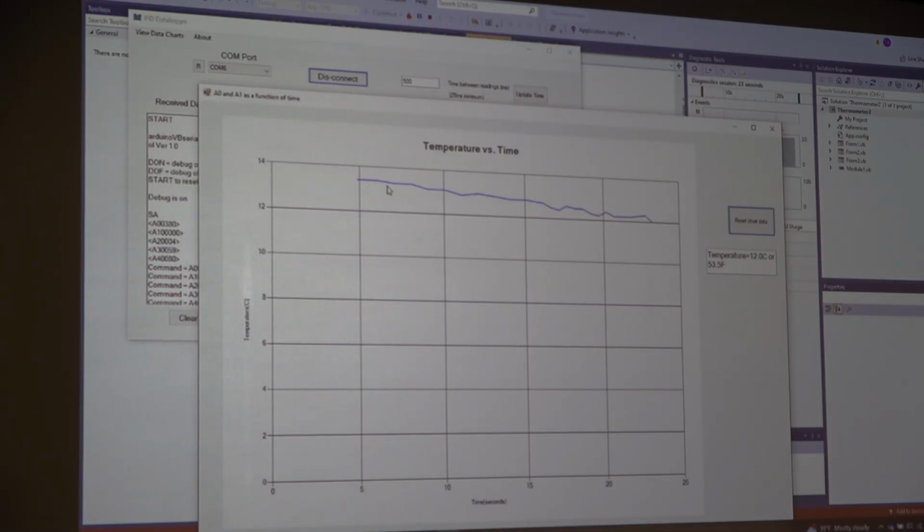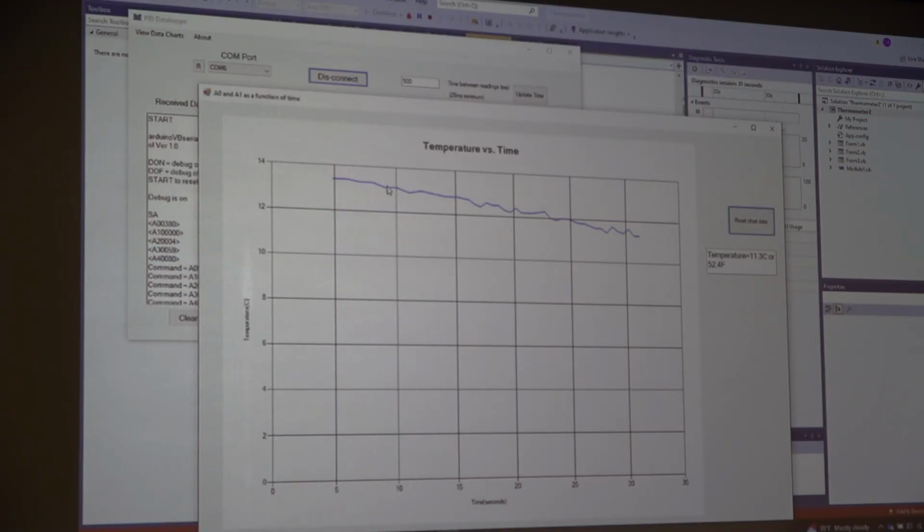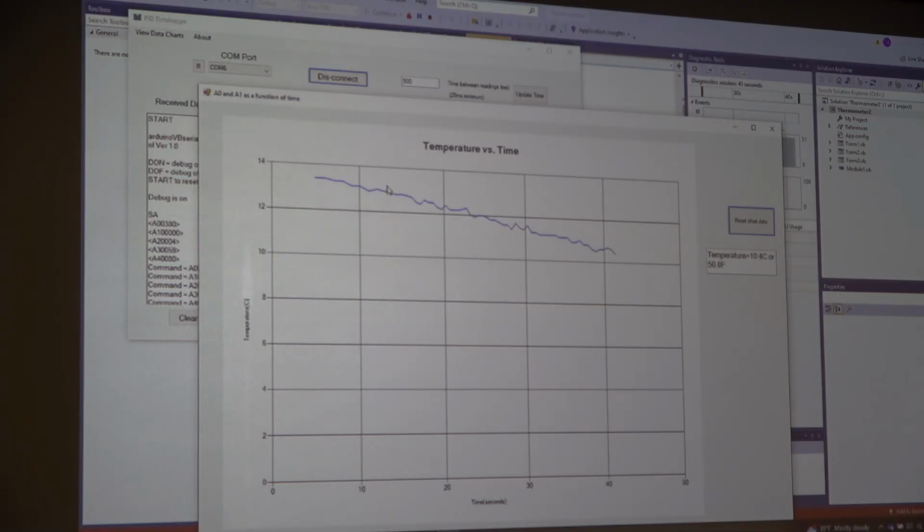When I was getting ready for the class, 0.05 was ringing pretty good. The difference was I was starting from about 20C. I wasn't feeling rushed to keep you guys engaged. If I had 10 minutes to make you sit there bored out of your minds, then we'd have much more time for that I value to build up, and we'd be hitting set point with way more throttle on.